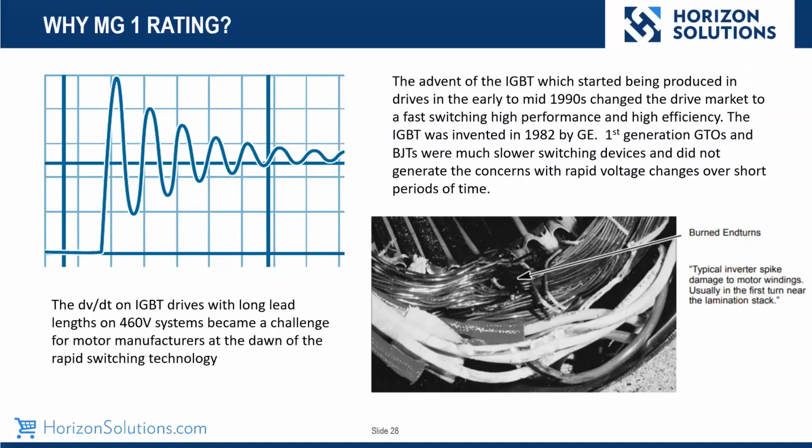We've got concerns with the rapid voltage change again. And now we're referring to reflected wave. So the two phenomena you have are your noise or your capacitive currents that you have to deal with in the motor, and you have to deal with the reflected wave that will cause issues that you see. It's showing this picture on the right with the red arrow, where this just punched a hole through the end turns of the motor. The corona built up, it got across there, then you got a short, then you lost your insulation, then you lost your motor.